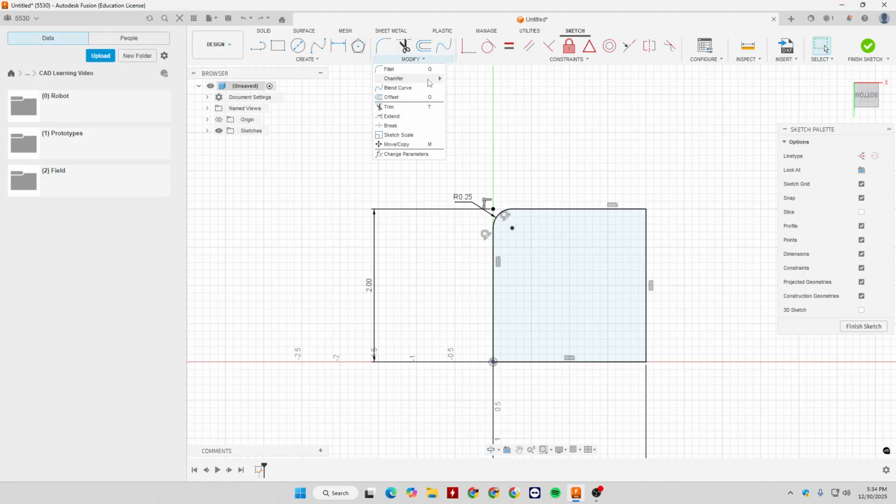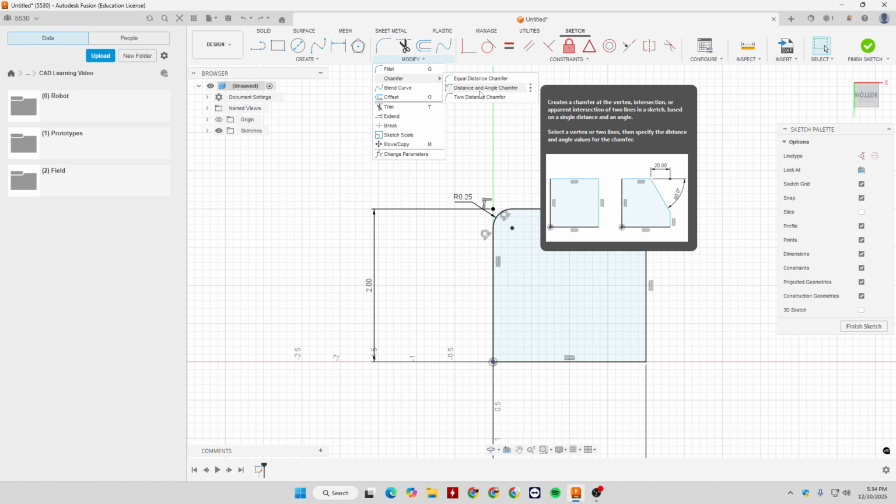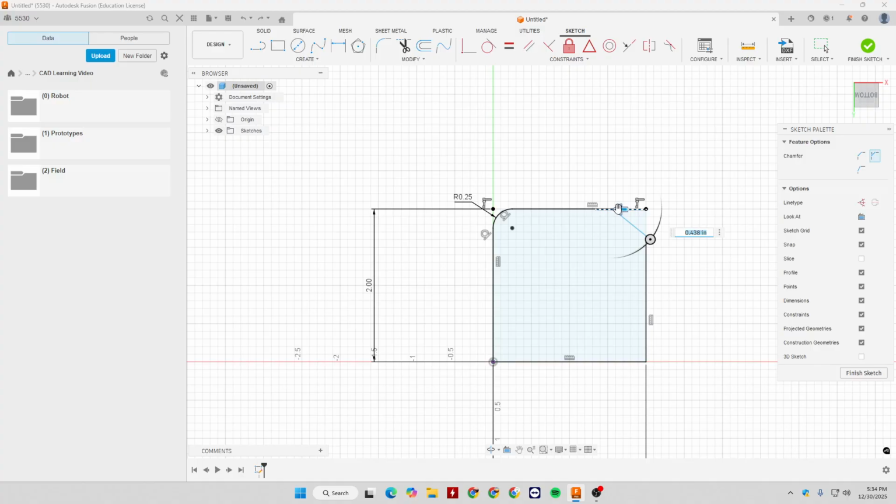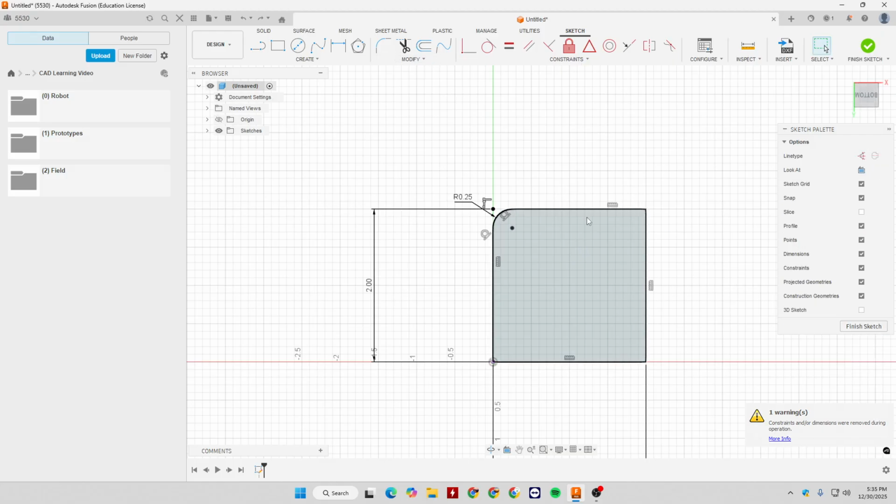Another chamfer that we can use is a distance and angle chamfer. So if we create the distance here of 1 inch and then do a 45-degree angle, this will be essentially our equal chamfer, but we can change that angle so that it's unequal, and we have a lot of options here, from obviously our 90-degree angle that we wouldn't do as anything, and then all the way down. It's kind of glitching out there. I guess it won't let us select that, but this has a different version of a non-equal chamfer, which we will find in this next one here.